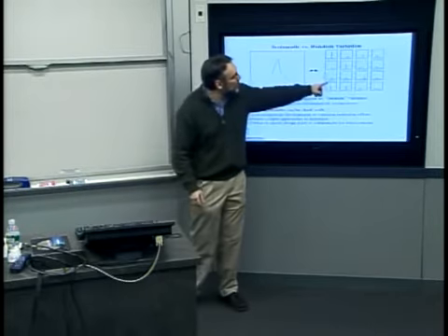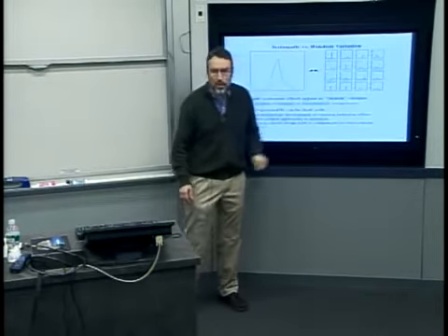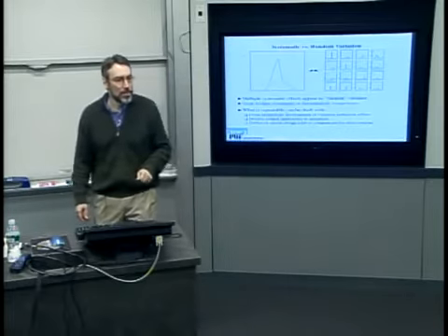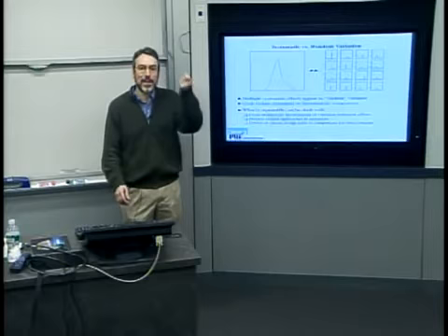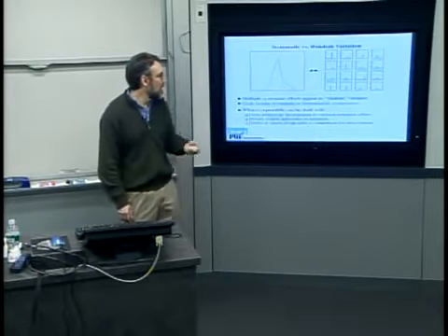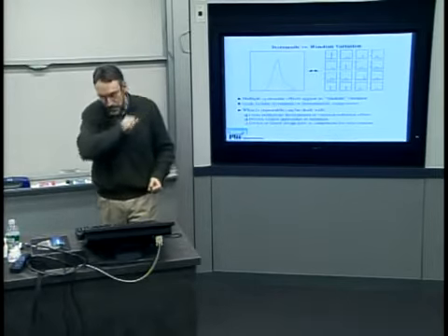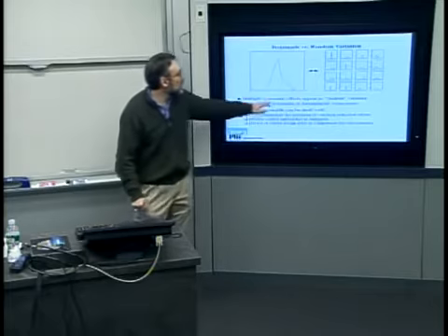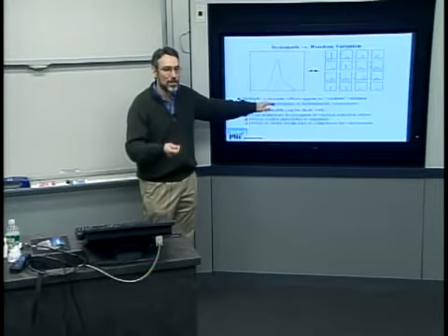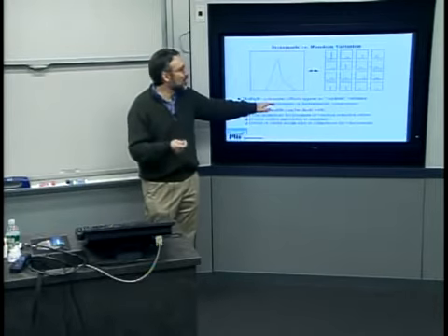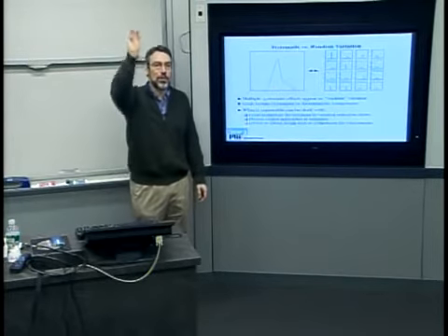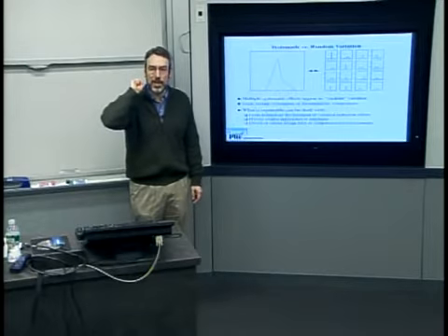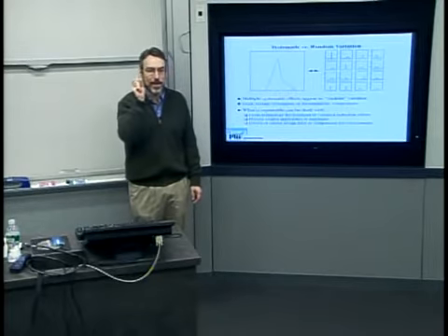What else is the case often is that some of these are not completely random. Many of the sources of variation have a systematic physical cause. And if we understand what is systematic or repeatable, every time you run this, you might actually find that the transistor in the upper right corner of the chip is a little bit too wide.